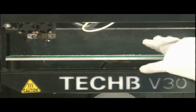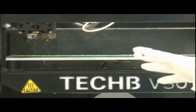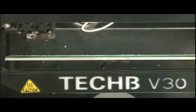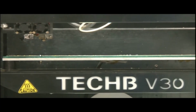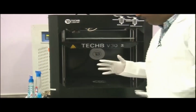The bed area maintains a soaking temperature of 50 to 65 degrees. It is actually the preparation of the table. It is heated to a specific temperature so that the material deposited here, whose temperature is about 200 degrees, can stick and set easily. So we deposit one layer upon another during fabrication or manufacturing.